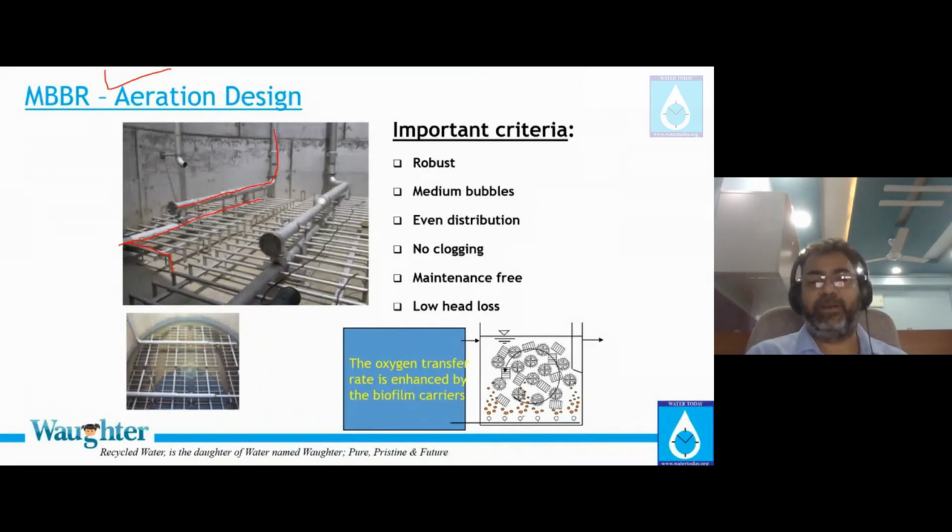Because you understand, even if you put a bubble here, there is so much plastic here to really hit and get it disintegrated. You do not require micro bubbling at all. You require something called medium bubble. The oxygen transfer rate is enhanced by biofilm carriers. This word is very, very important.